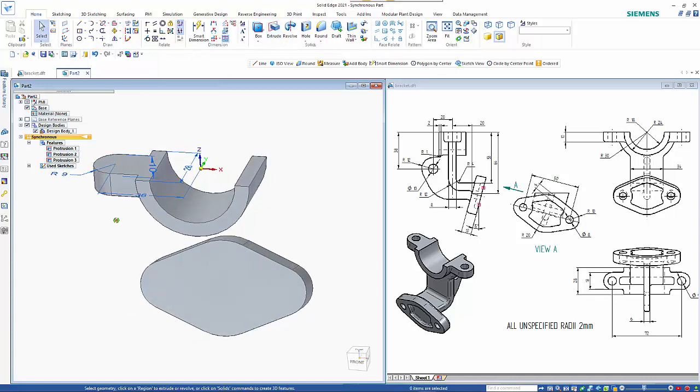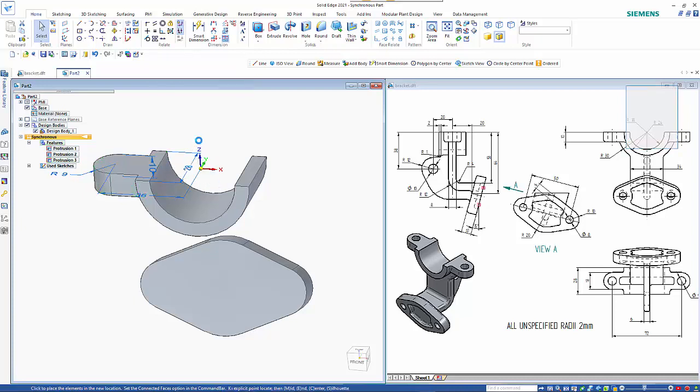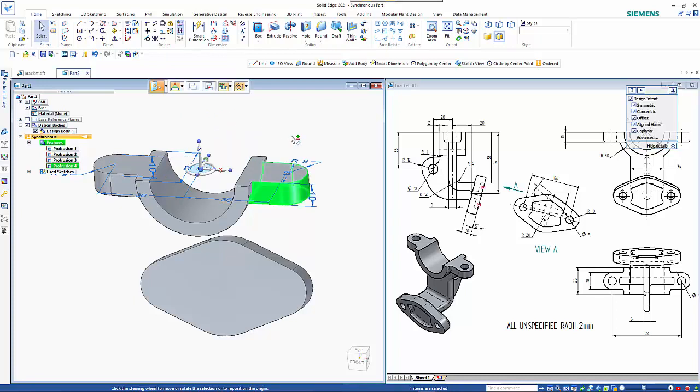and drop that down 10 mil. So if I want to sort of mirror or rotate that around, I can select that, hold the control key down and select that top face so that I've got the whole closed profile. I can then come up here to the copy command, position the steering wheel in the center and then just drag that around 180 degrees and that sort of attaches back in.